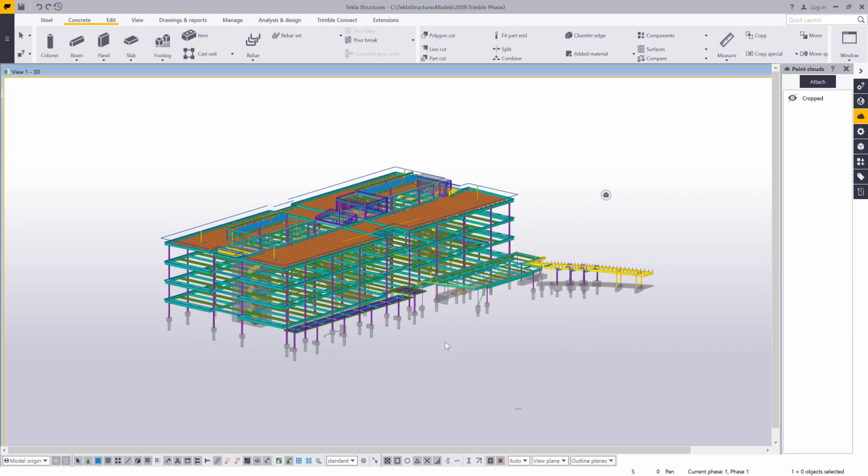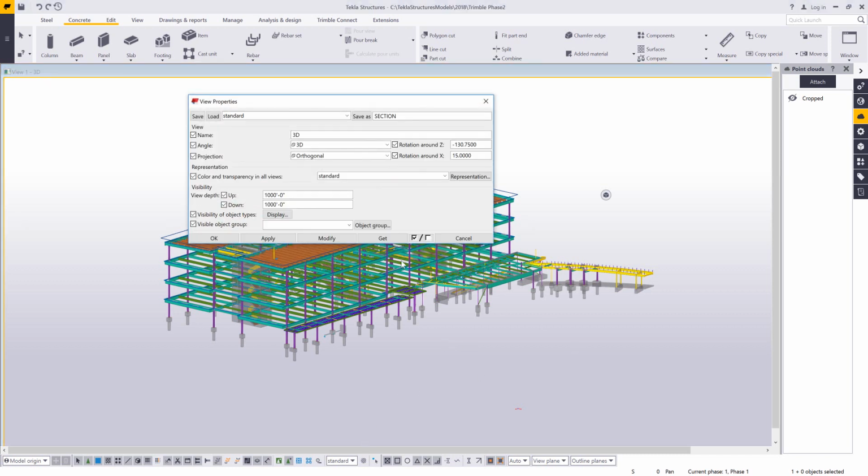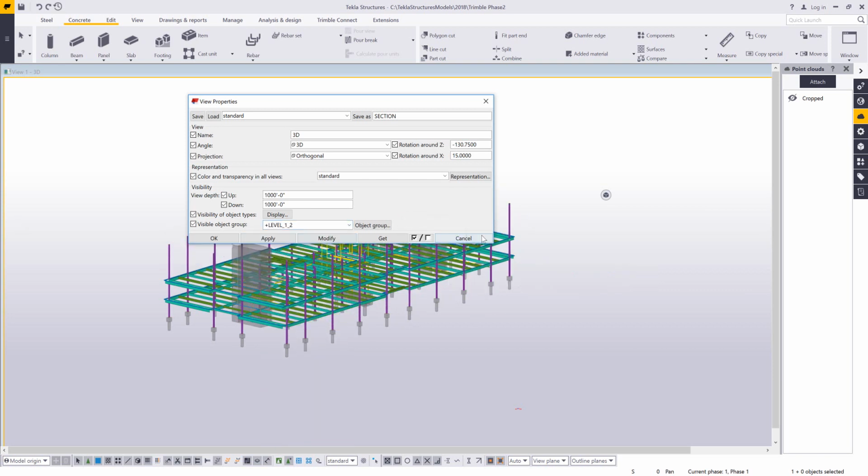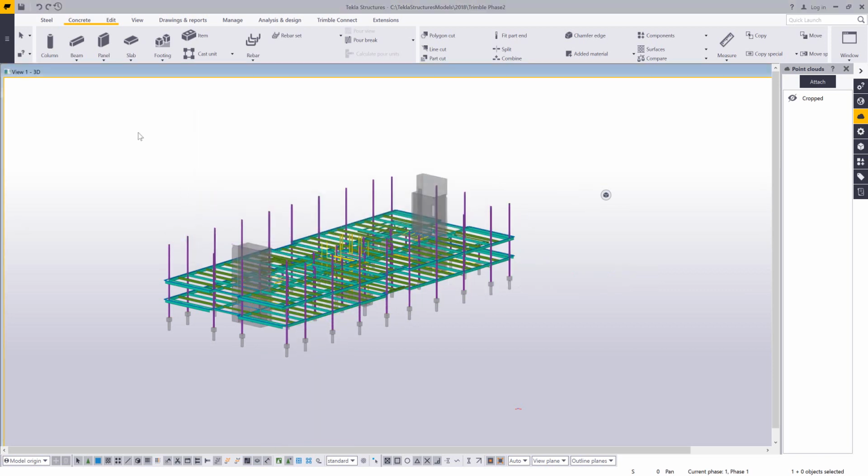As we've seen, we just did the scan on the first two floors. So I'm going to come in here and filter out just level 1, hit modify there, and then window highlight this area right here. This is what I want to export to David so that he can compare this in RealWorks to the point cloud scan.